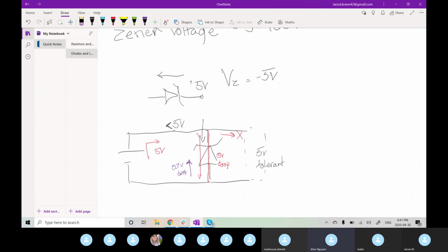Just to let you know, some teams even use the Zener diodes as a regulator, instead of the LDO. Yeah, but they burn a lot of power, so it's not really recommended. Yeah, I remember Koi talking about that once. But it is definitely not the best way. But super useful, used everywhere. It's on the VCU, it's on the BMS. It's a very common thing. So primary being the voltage cutoff, useful for protection. Any other questions on it?